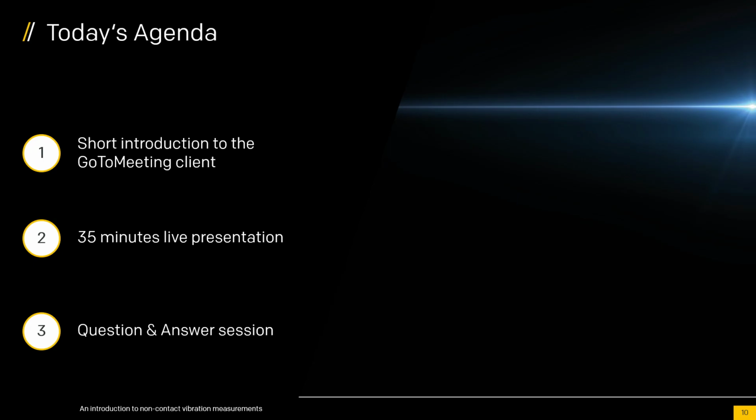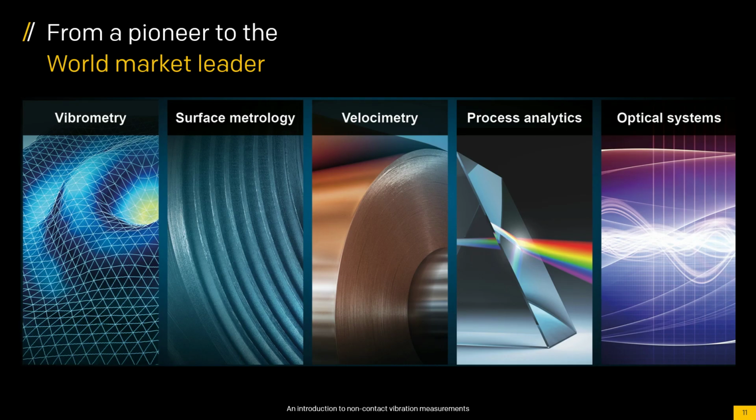Yes, they are tricky because if you go back to the basics of interferometry, a vibrometer is fundamentally measuring the component in the direction of the laser beam. Now, in this particular attendee's case, there is always motion perpendicular to the laser beam, so it's going to add noise to the data.